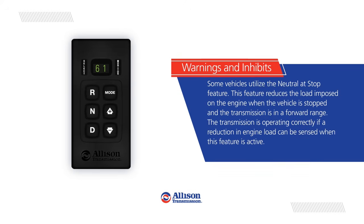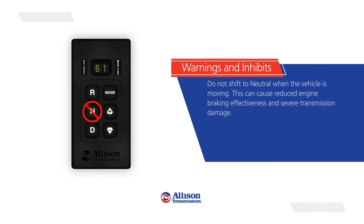Some vehicles utilize the neutral at stop feature. This feature reduces the load imposed on the engine when the vehicle is stopped and the transmission is in a forward range. The transmission is operating correctly if a reduction in engine load can be sensed when this feature is active. Do not shift to neutral when the vehicle is moving.